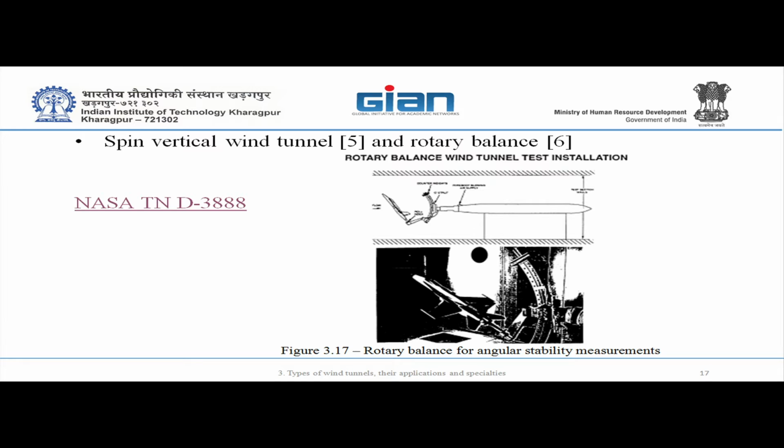But once you need dynamic coefficients, you need some dynamic facilities to extract them. So if you need pitch moment damping, you have something with flexible mounting, and you check what is your damping coefficient for any certain configuration.